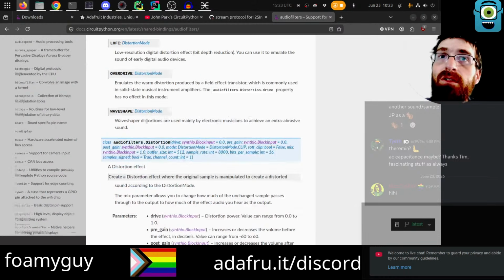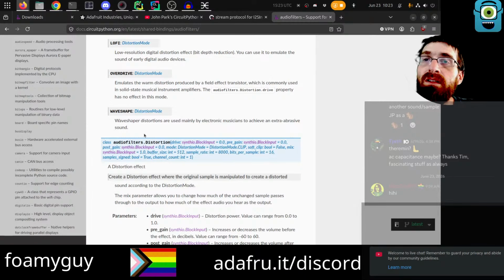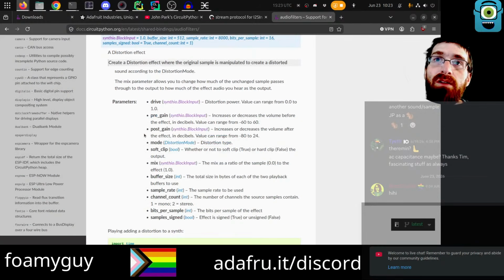I2S out, audio out, all these things, they can be chained together. So you can get a source, send that source into an effect, send the result of that into another effect, another effect, another effect. You can pipe all of those into an audio mixer to change the volume on them, and then at the end of the chain, you can send it to an actual output like a real speaker.